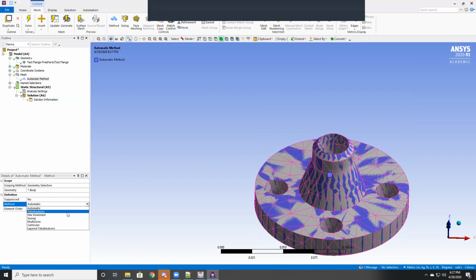There's a lot of different cases where you want a lot of different kinds of meshes. So in most cases, you're going to want to figure out what works best for your condition. I cannot promise you a catch-all solution because every problem is different. In most cases, I've found tetrahedrons to be useful. And so if we just set that to tetrahedrons, there's now this algorithm of patch conforming or patch independent is the other option.